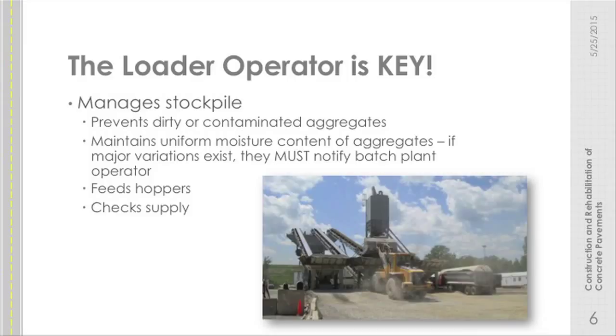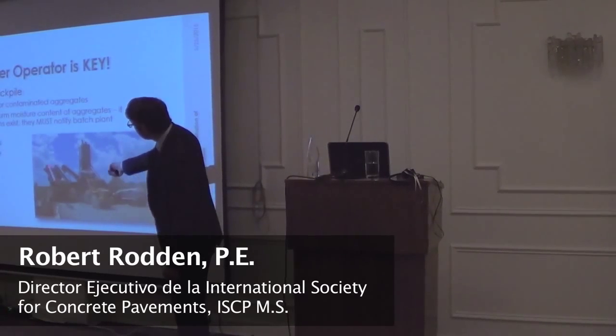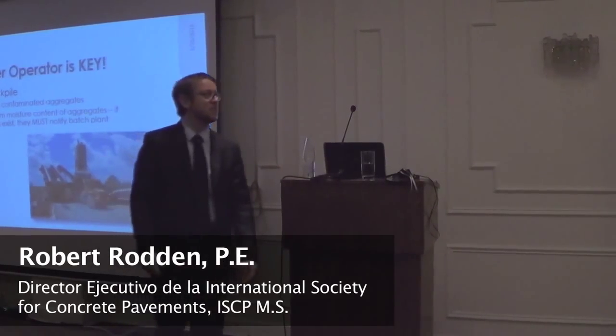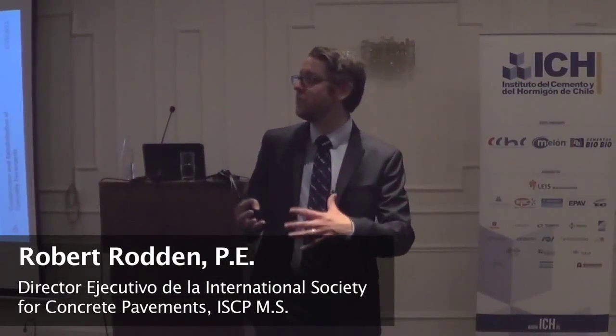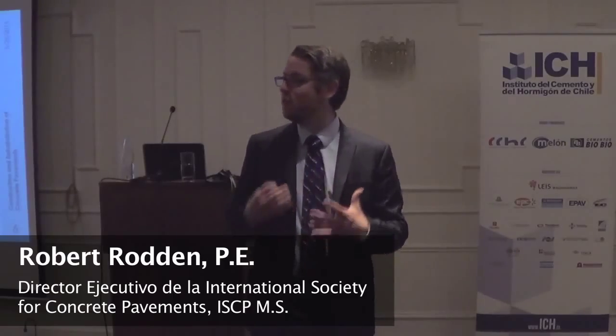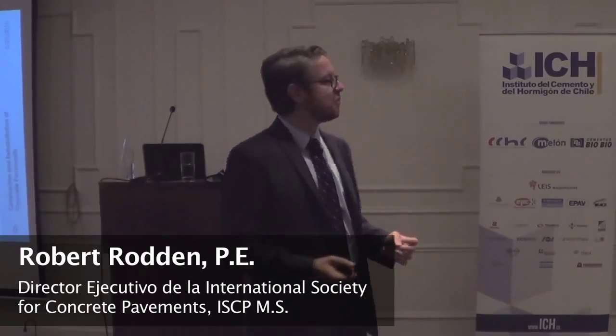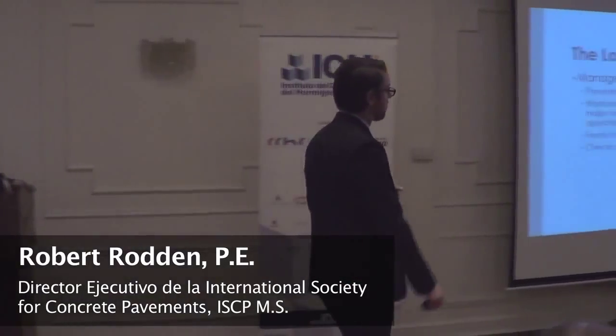So it's someone's responsibility to work that material, to make sure it has a uniform moisture content, and to constantly supply enough of that aggregate into hoppers, which will then get pulled from and weighed during the batching operation. So this stockpile management, this moving around of materials and maintaining a uniform moisture content is the responsibility of the loader operator.